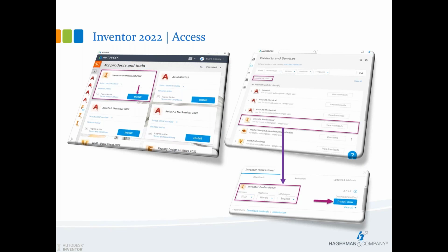Let's see, here's some other questions coming in. Show constraint state, is that a document setting only? For legacy files, anything created pre-Inventor 2022, yes, that would be the case. Any new file started with 2022 templates will have the show constraint state turned on by default. Those are saved locally in the document, unless somebody opens the template, disables that and saves the document.